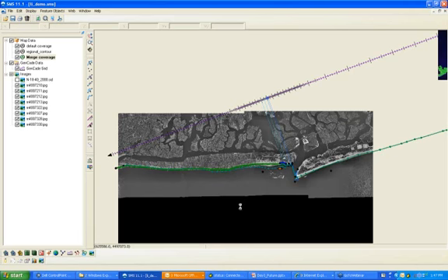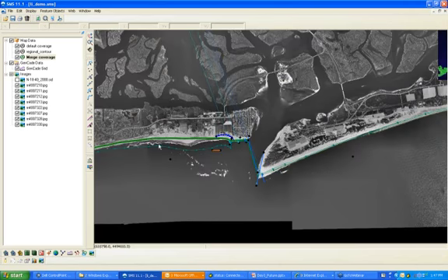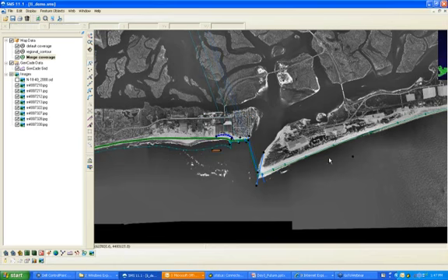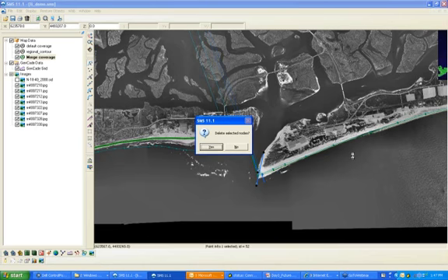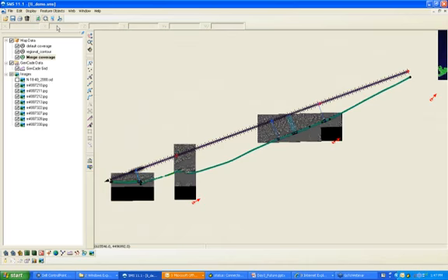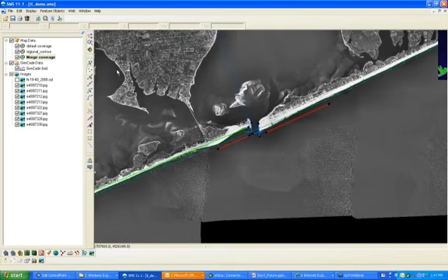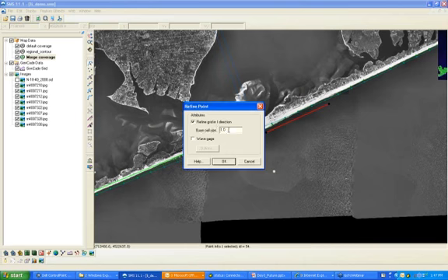One other thing before I finish this case is there's another option here. So I'm going to remove these wave gauges. This can be done by clicking it once, hitting the delete button, and saying yes. So in a second example, you may want additional information here. We can also say that we just want 1 point here, and we want it to grow outside of that. And we're going to say the base cell size of 50 feet.